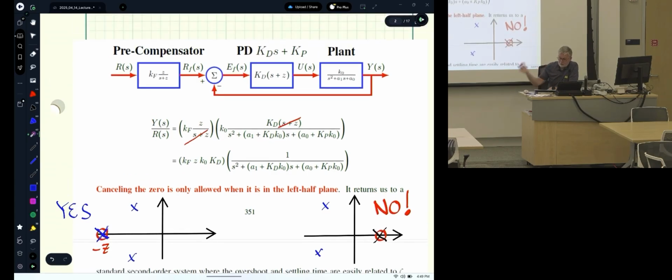And then that will have it such that if we command 1 meter per second here, we get 1 meter per second here, whereas if the DC gain is 0.8, we command a meter per second here and we get 0.8 here, or if it's 3, we get 3 meters per second here. So if this is going to be a command, a reference for us, it's nice to use that freedom. Okay, so that's just algebra.